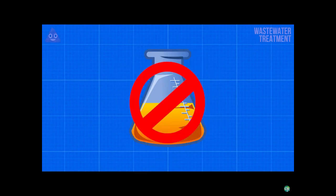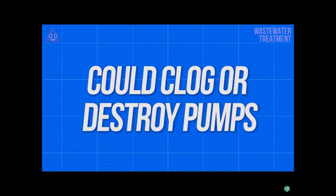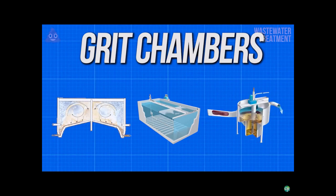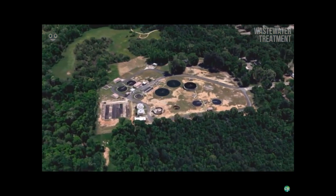There are three types of grit chambers: horizontal grit chambers, aerated grit chambers, and vortex grit chambers, which all accomplish the same task using slightly different methods. Following the grit chambers, the sewage will move on to the primary treatment process, which starts with a large basin called a primary clarifier.